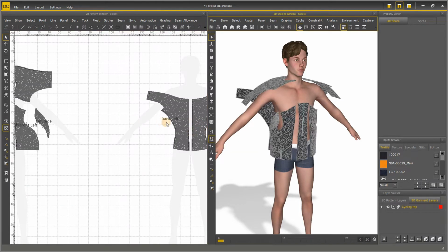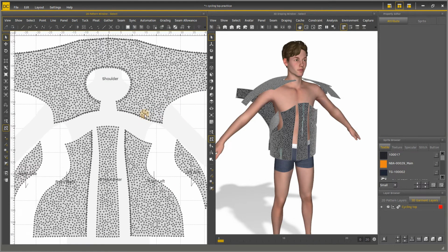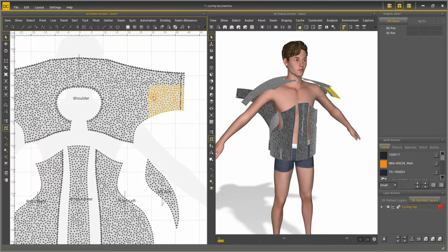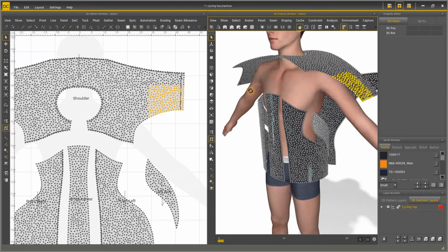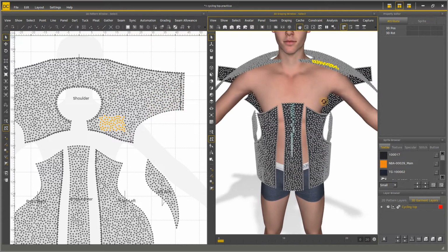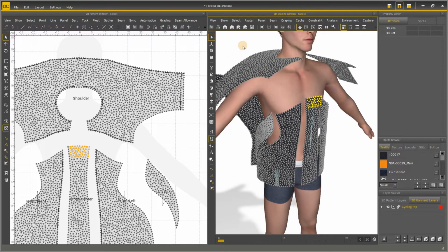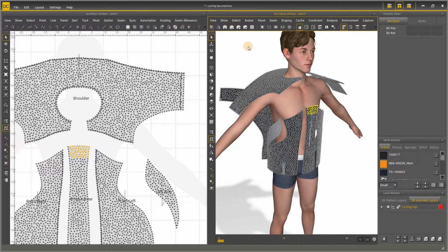When we are in this mode, only vertices can be selected and we can do the manipulation by selecting the vertices. Usually, it is safer to select the vertices in the 2D window because it is easy to select other vertices you don't actually want in the 3D environment.